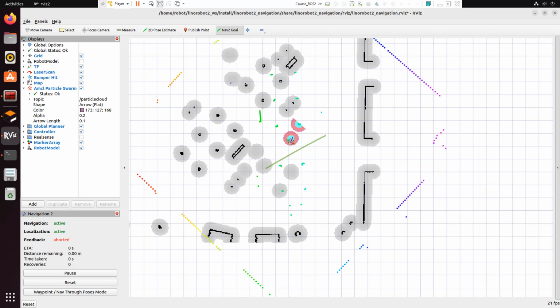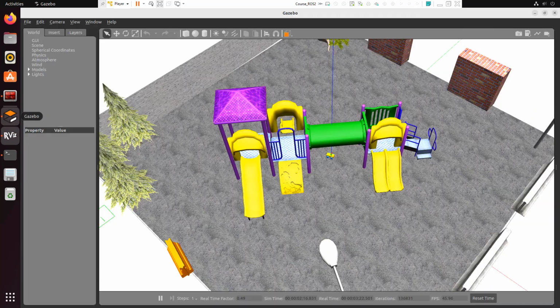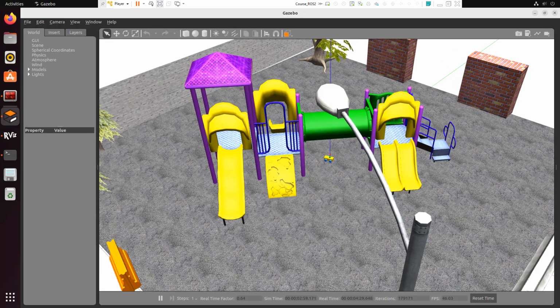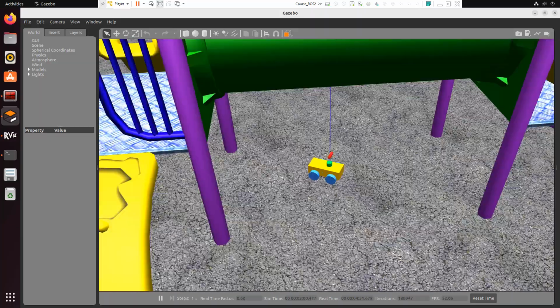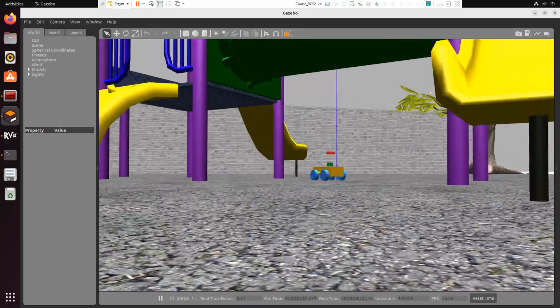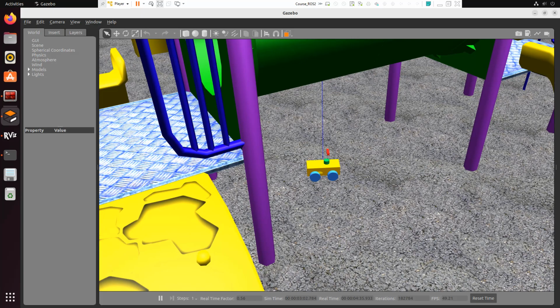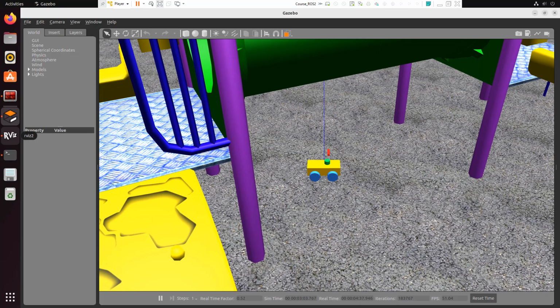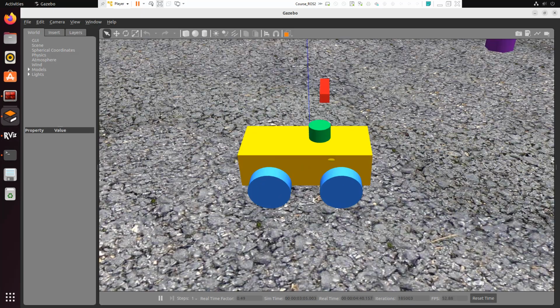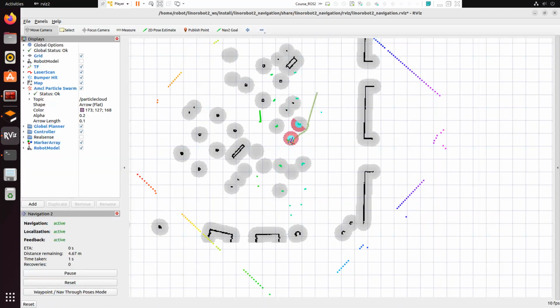So that's why the robot can't move. That is again tricky, because there is no obstacle around the robot. So maybe something else is interrupting the view. Maybe the robot itself is being detected as an obstacle.